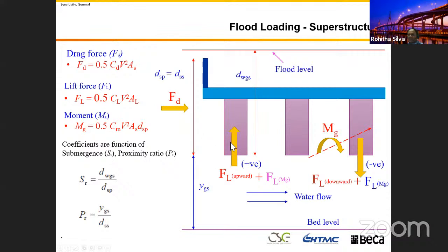We discussed this under the articulation. I will put a slide to discuss how to hold down the bridge. Someone says it's easy. You put the post PT bar in here, attach it to the bridge deck, and put a nut in there. It will hold the bridge down. Yeah, you can do that. But remember, when you put in all this restraint system, you need to make sure that the bridge is moving in and out all the time. You need to make sure that you allow for that.